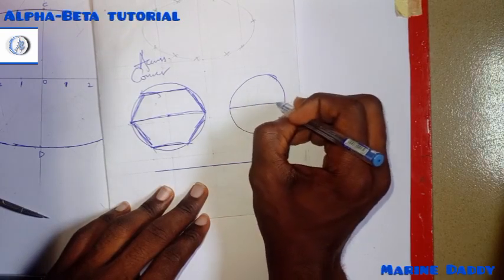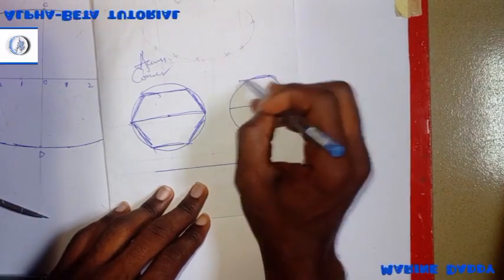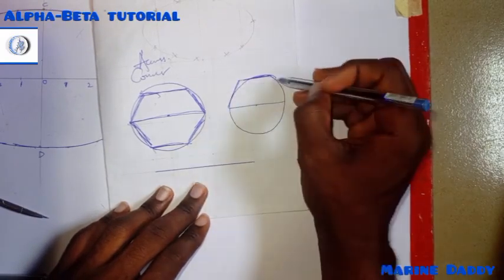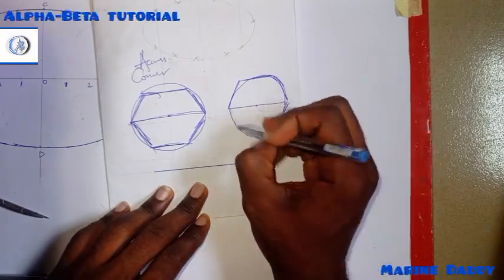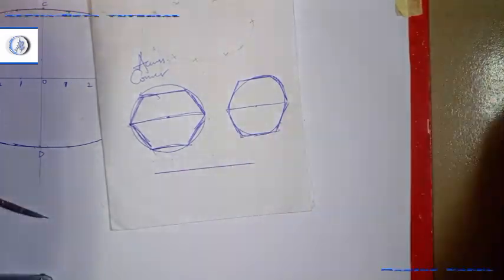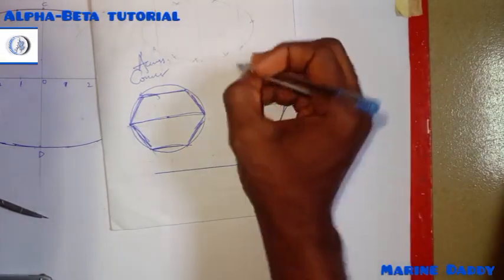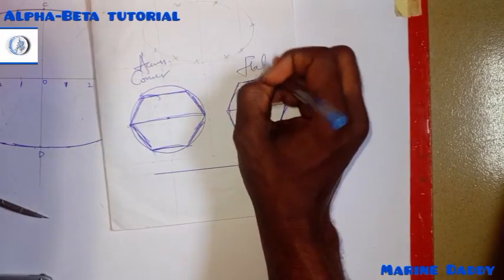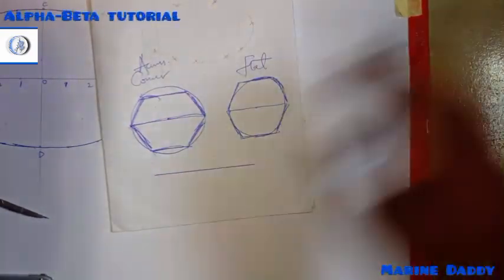When you now hear across flats, this is what they mean by across flats. You will be given the distance across flats as usual. That's the diameter. Across flats means it's going to be constructed on top of the circle. You understand? On top of the circle. So that's what across flats is. This one is across corners. So you need to take note of that.